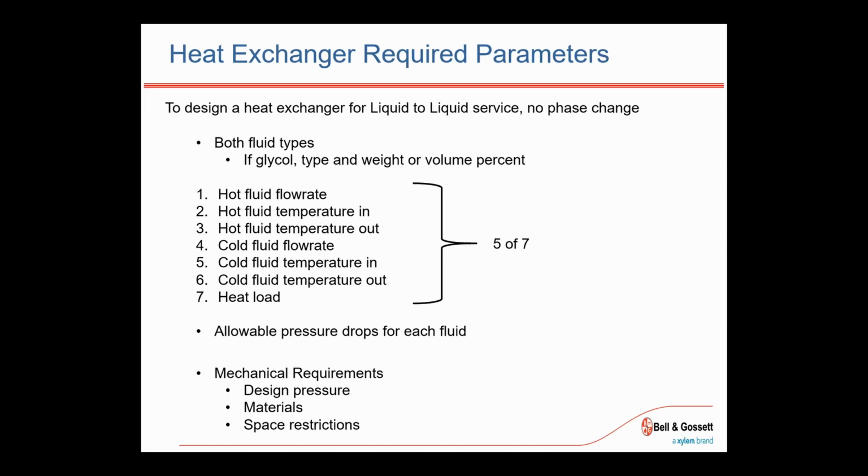Later on, we'll talk a bit about some of the considerations with pumps, but with heat exchangers it's the same thing. Today, for instance, we had height constraints in a room, but we also had limited floor space. So it's trying to figure out the balance: the smaller we make that approach temperature could potentially give us a really tall unit. Then that unit may have a very large frame, and that frame may not be able to be reduced.